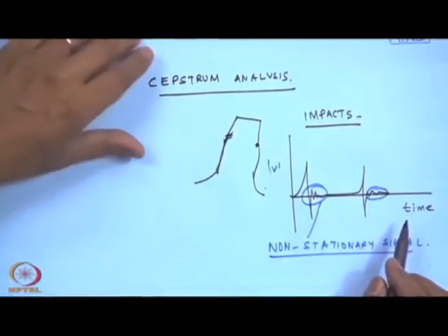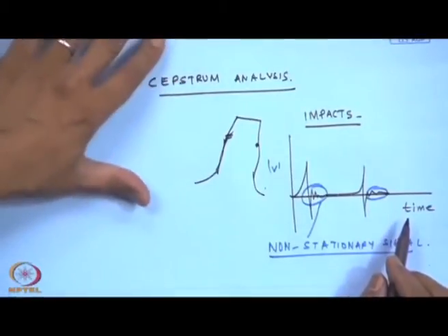So, the fundamental signal processing theorems of stationary signals, wherein the properties of the single ensemble over a given time change, are being violated, and thus stationary signal analysis like FFT etc., cannot be done on such signals. So, we have to do signal analysis using non-stationary techniques like the wavelets.